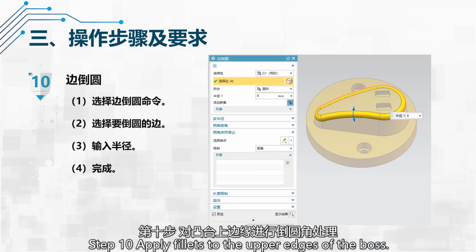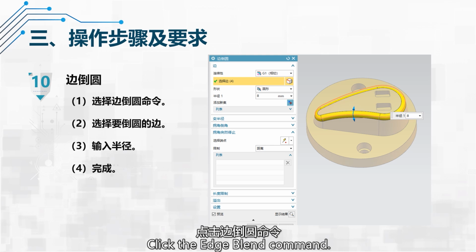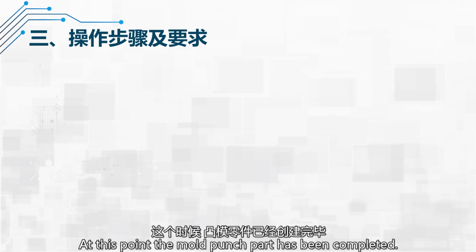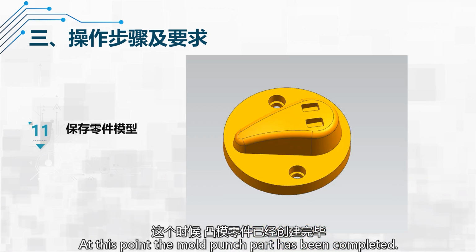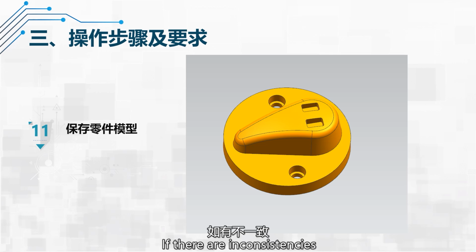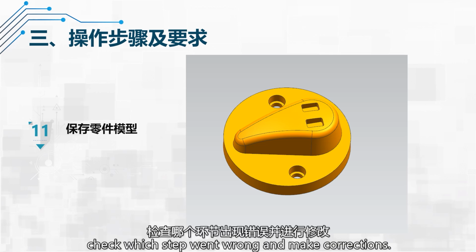Step 10. Apply fillets to the upper edge of the boss. Click the Edge Blend command. Select the edge to fillet, input the fillet radius, and click Confirm to complete. At this point, the mold punch part has been completed. Compare it with the drawing to check if the model matches. If there are inconsistencies, check which step went wrong and make corrections.